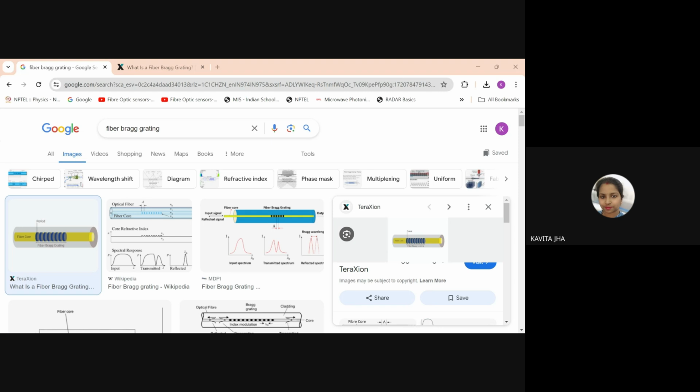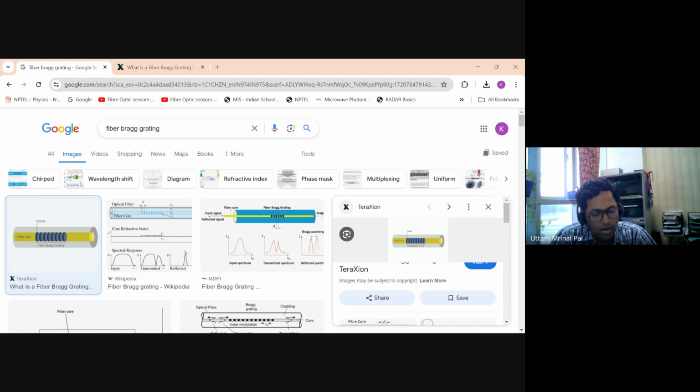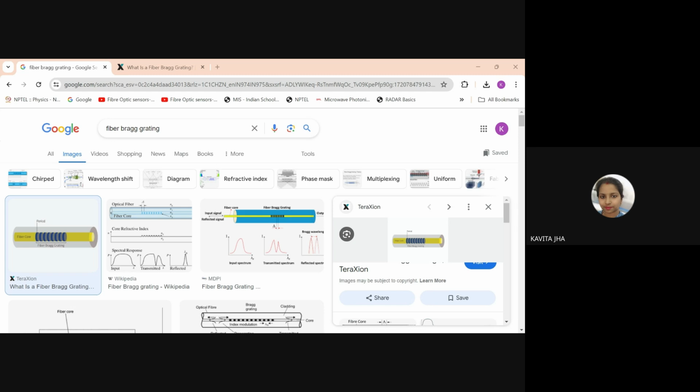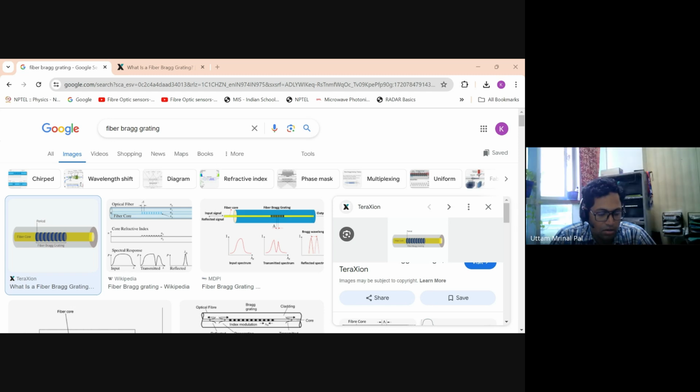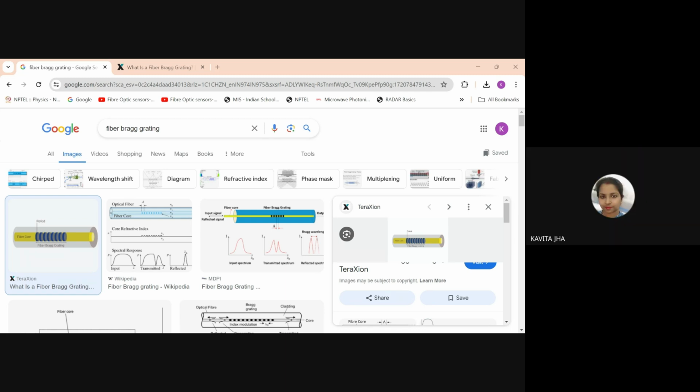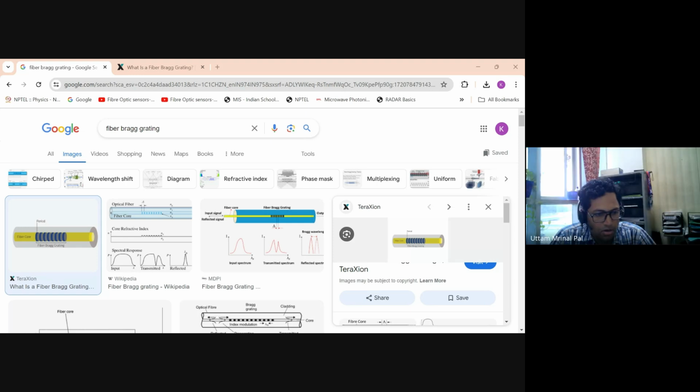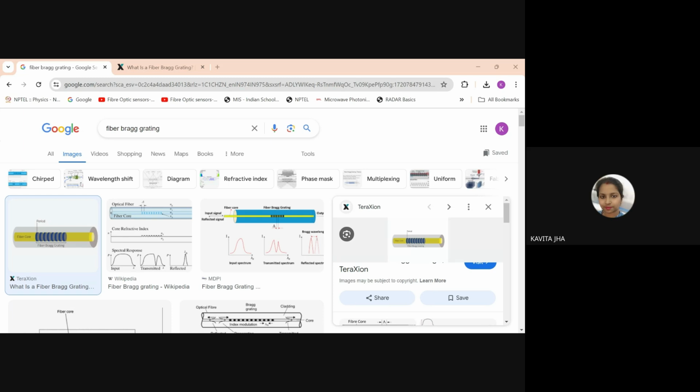So first I should make it for the entire geometry, then reduce the numbers, and then go further. You can keep the same numbers as well. Ideally, first make a simple core and see how the wave is propagating. Then add a single layer, then two layers, and go on increasing the number of layers. This longitudinal cross section will not be much difficult. When you do it in 3D, then it is going to be difficult.